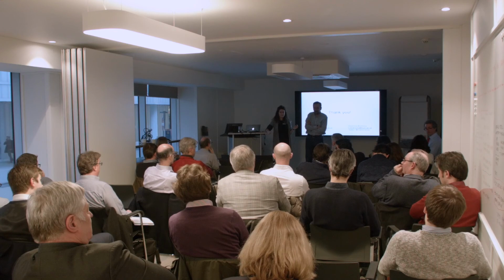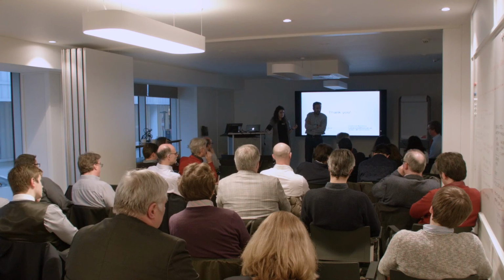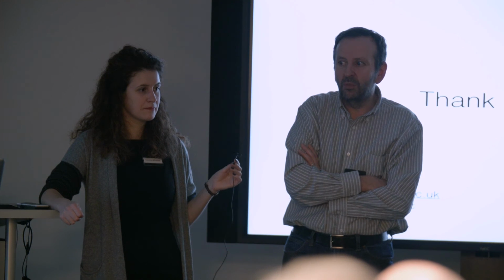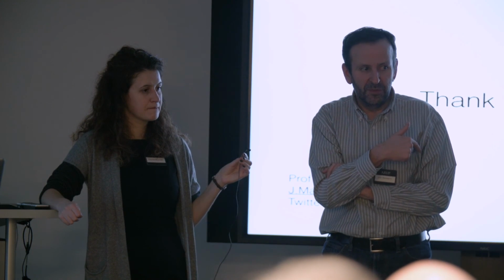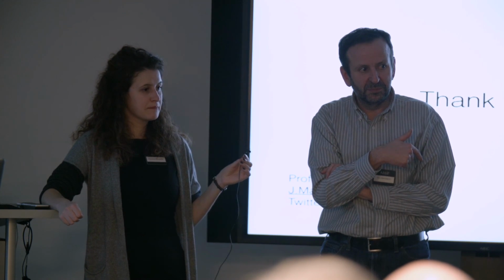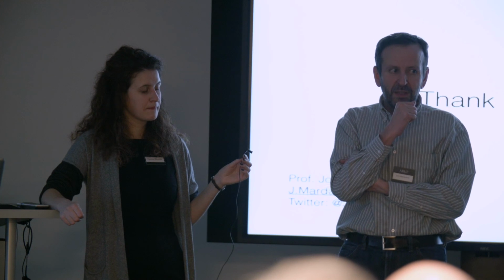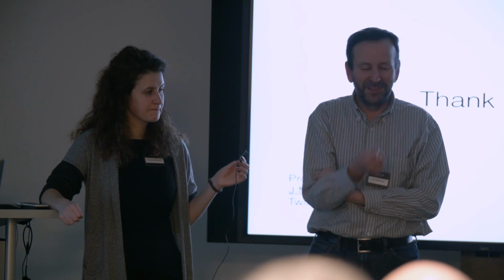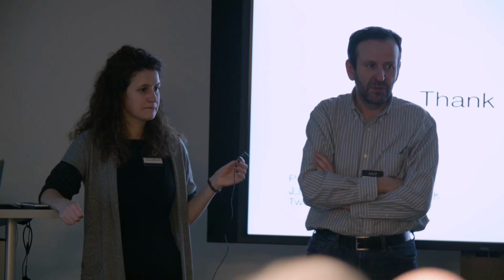Can I just ask one last question? Where in this workflow does the G value of the glass play a role? But it doesn't, because it's a total energy, and we've just been looking at visible light. Because we're only relating it to the sky luminance. The solar energy is only affecting the sky luminance. It's the visible part of it. Yeah, so that's why it's the luminance. Even though Radiance is called Radiance, we always just use a shortwave model for reflectance and transmission values.